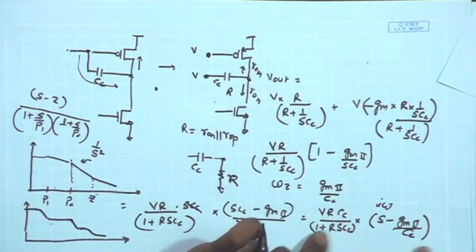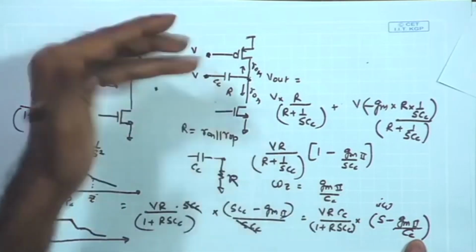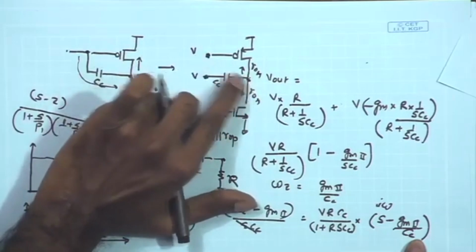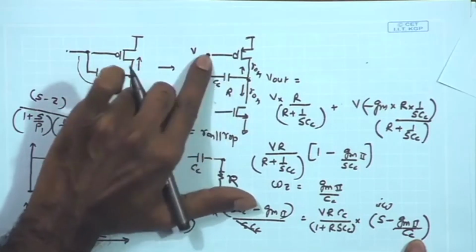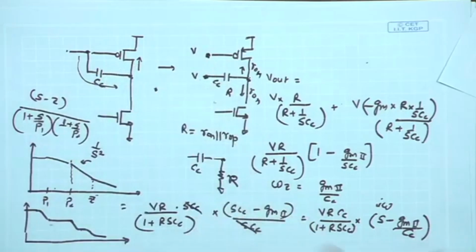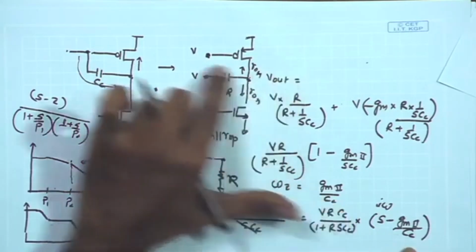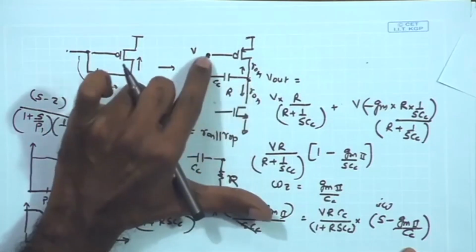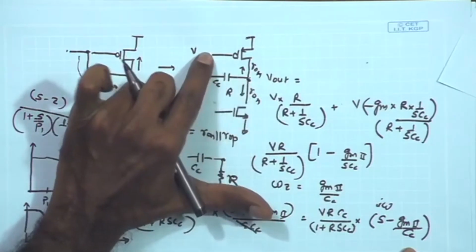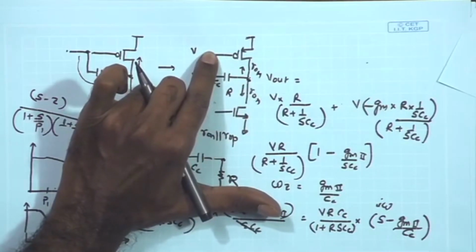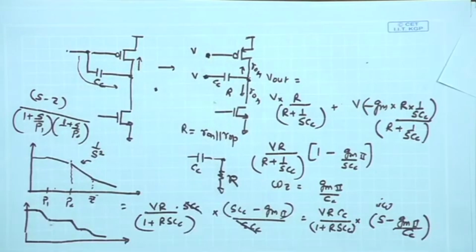So, here just to show the effect of the 0, and without considering the degrading impedance over here and the drain and gate getting short circuited, those things have not been incorporated over here. So, this is just using first order equations just to show how the 0 is appearing, without considering the other effect where the CC connecting the drain and gate is effectively getting short circuited, and it is reducing the impedance, which is pushing that pole to high frequency.